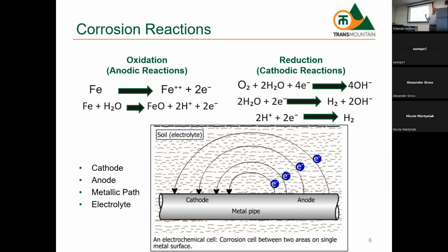On the cathodic site, and remember, the intended purpose of cathodic protection is to turn all of the surface area that is exposed, potentially corroding, to cathodic. And as we apply cathodic protection, these are the reactions that are taking place. So why does the pH go up? OH minus. Answer that one.